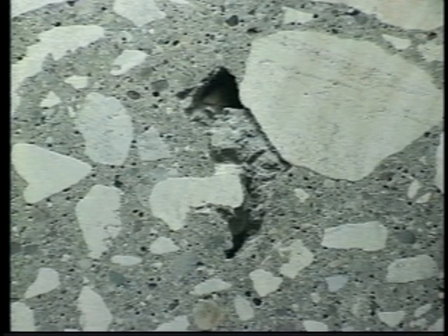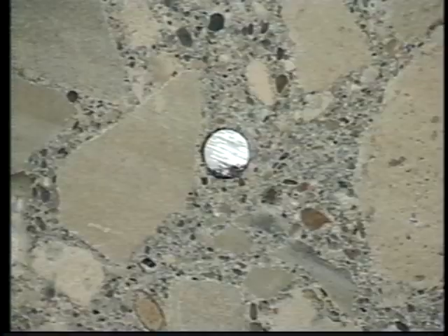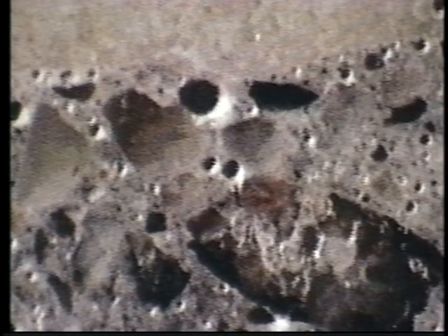Capillary porosity should not be confused with entrapped air voids, bleed water, or entrained air voids. The entrapped air void shown in this picture results from poor consolidation. Bleed water moves through fresh concrete during the first hours and can collect under aggregate or rebar as shown in this picture. The gap under the rebar is due to bleed water and can be a site for corrosion in the future. Entrained air is put into concrete on purpose to provide frost resistance. Voids and entrained air are important factors in real materials that can have great influence on properties.